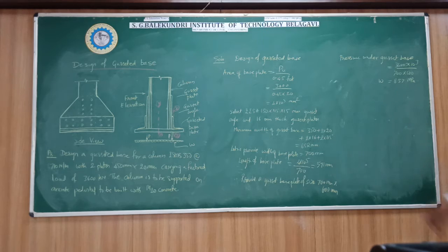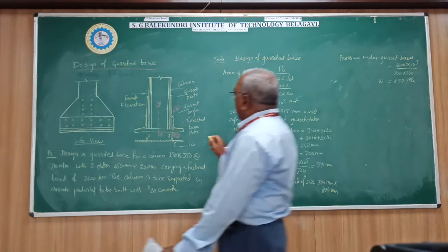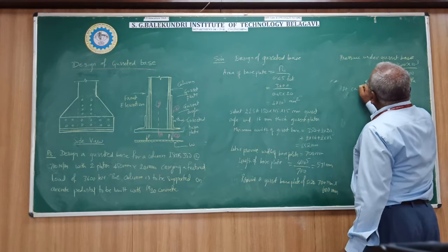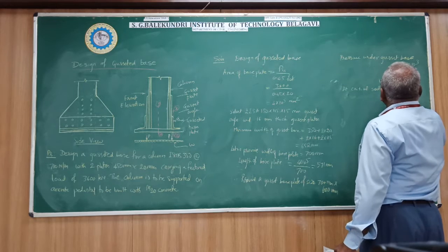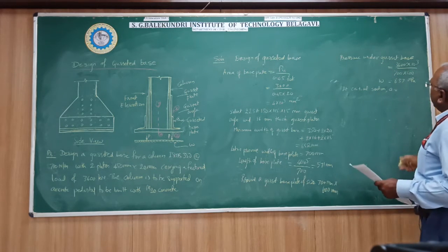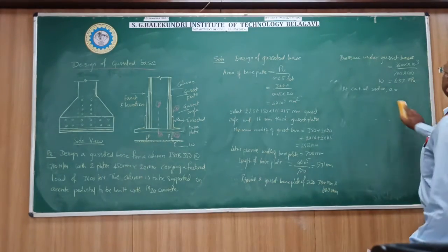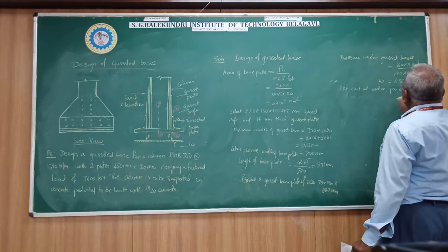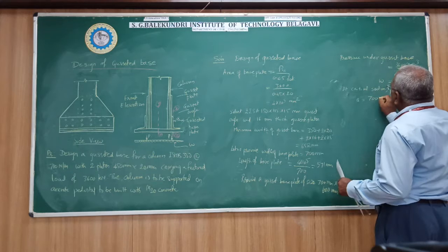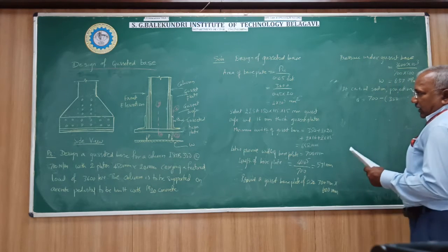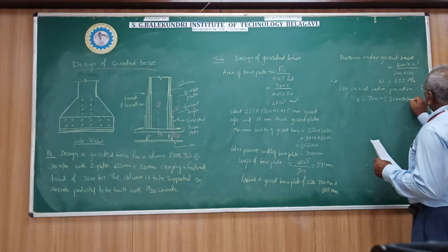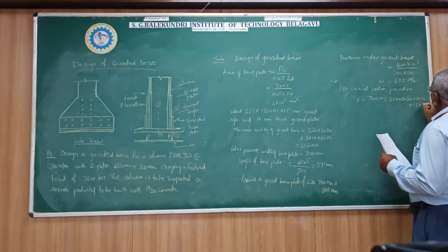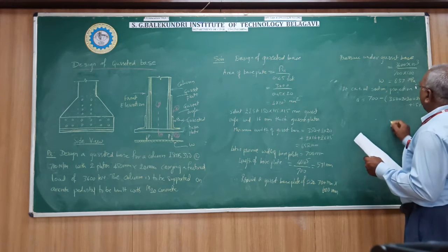Now the critical section is taken at XX. This is projection A. At the critical section, A is equal to the total width of the base plate, 700, minus the column size 350, plus two cover plates of 20 mm, plus two gusset plates of 16 mm, plus the thickness of the angle 15 mm, on both sides.